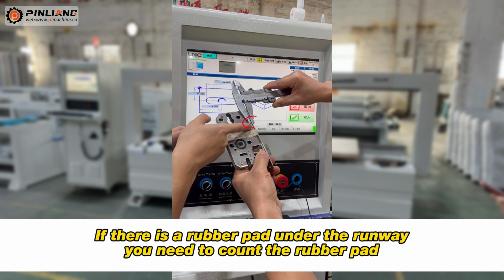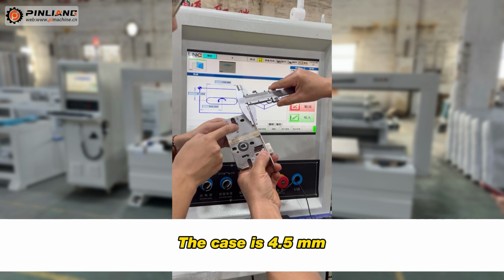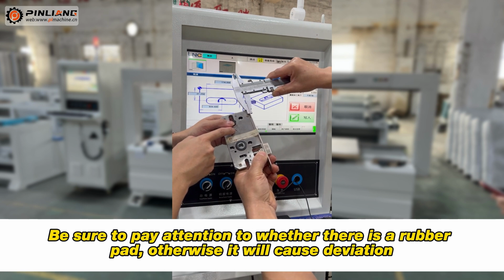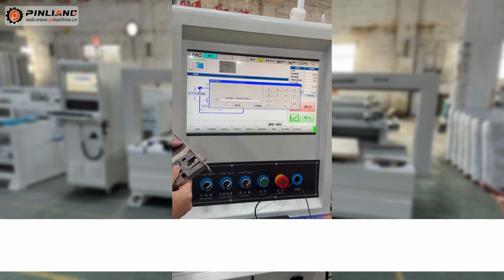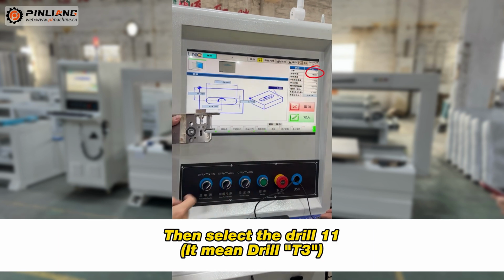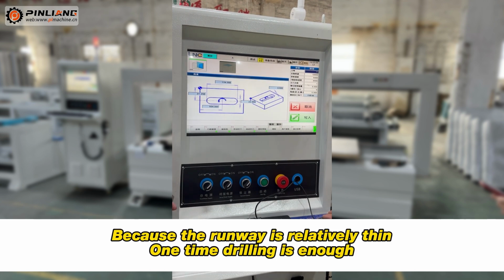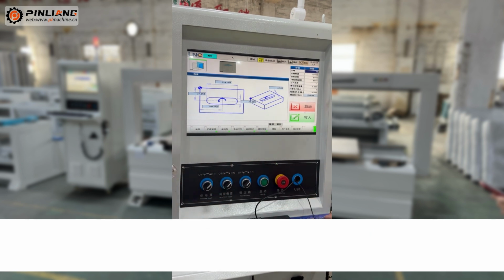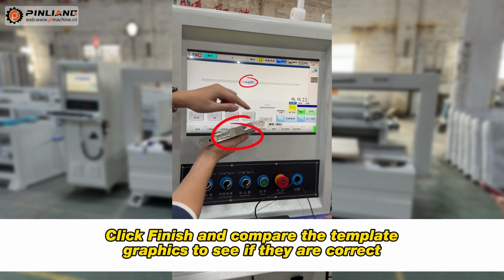If there is a rubber pad under the runway, you need to count the rubber pad. The case is 4.5 mm. Be sure to pay attention to whether there is a rubber pad, otherwise it will cause deviation. Then select the drill 11. Because the runway is relatively thin, one time of drilling is enough. Click Finish and compare the template graphics to see if they are correct.